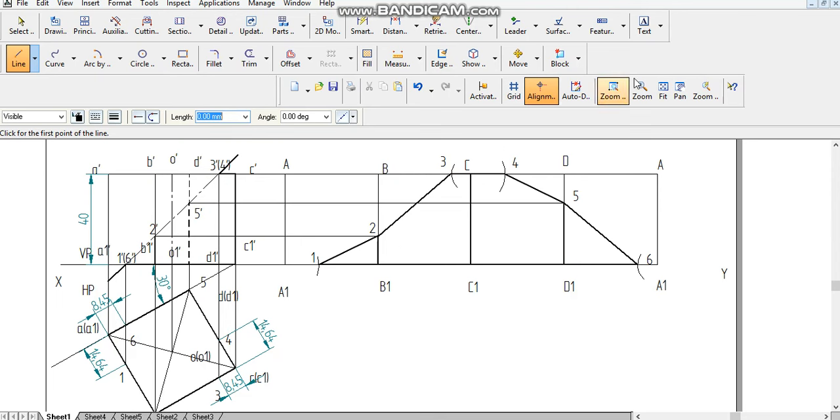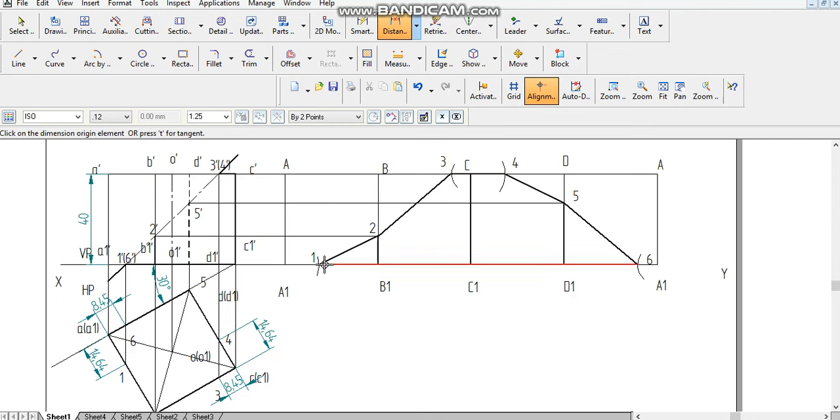In the next step, don't forget to mention the dimension of the cutting points. Select the distance between cutting point number 1 and this line. It is 14.64. And again, the distance of the cutting point number 3 is 8.45 millimeter. The distance of the cutting point number 4 is 14.64 millimeter. Similarly, this cutting point distance is 8.45. In the meantime, you have to select the distance between command and find out each distance between the base edges A to B, B to C, like that.